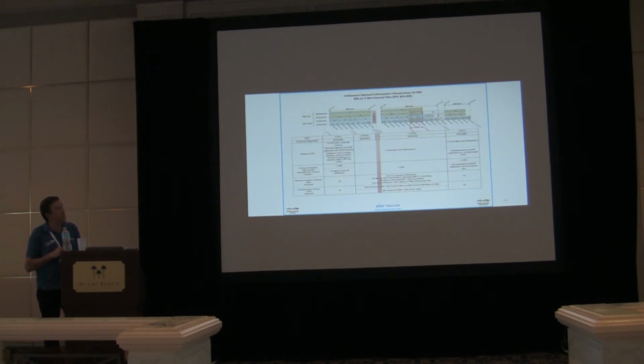And on the flip side of it, if you ever try to figure this one out, I've done it for you. This is the UNII, the 5 gigahertz frequencies in the US if you're using them. It gives you all the channels, the rules that apply to you and how you use them, where they guard band things, where the TDWR radar is, and just a lot of useful information on the wireless side. So anybody wants those, I'll have them afterwards. You can just grab hold of me today, or I'll be around all day tomorrow. I can give you one. Could be pretty useful for you.